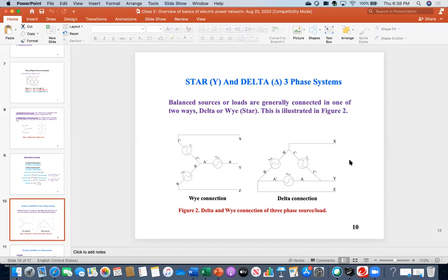For this 100 miles, there will be only delta connection just to save the cost of the fourth line. We will not place the Y connection because it needs the neutral. Instead, place the delta connection and just transmit the three-phase power, because we don't need to use the power for those 100 or 200 miles. But when you need to use the power, convert from delta to Y because you need the neutral connection for safety purposes.